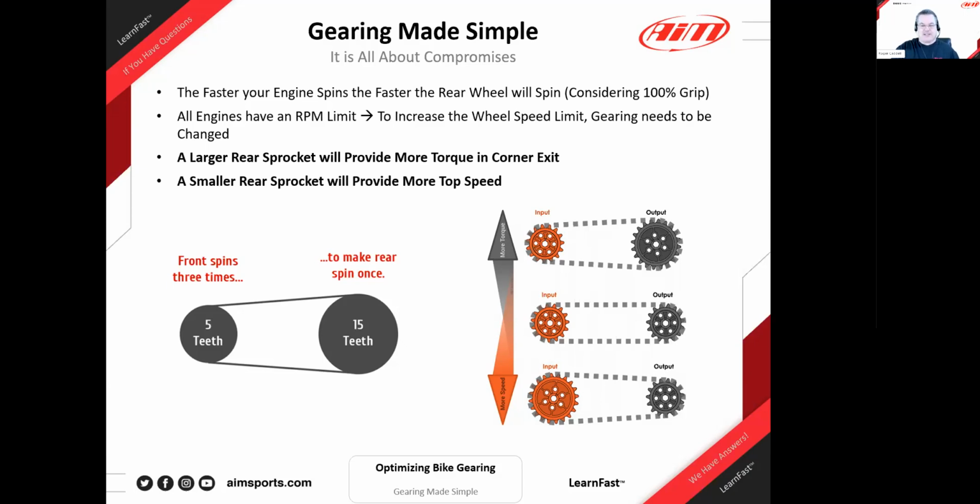changing the wheelbase, which in most forms of motorsports, when you're at the limit, is a tuning thing, right? The length of that wheelbase is important on a bike, even more so because of the forces that are happening the other way too. We're very fortunate in motorcycle racing that we can make a gearing change at the wall. So it's a very good knob, and that's why it's such an important knob that we have to consider when going to a new track. It's really the first step in getting your bike set up. And like we said, it affects your chassis, your squat and anti-squat, and your bike geometry.